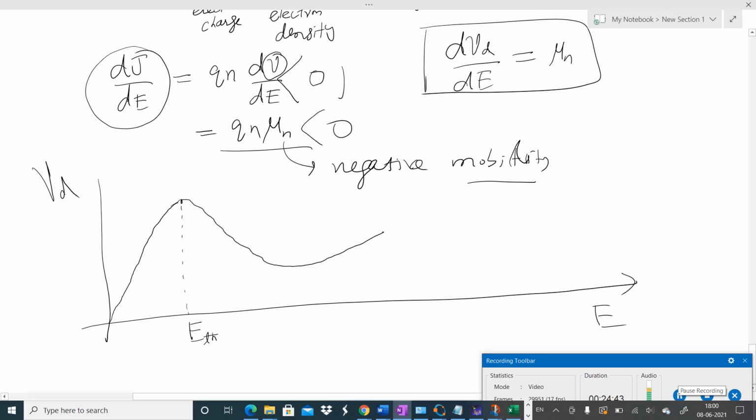And you know that usually, when you have a usual semiconductor, you have this line where mu L is equal to drift velocity by electric field, right? So actually your device should behave like this. Now, because of the satellite valley, because of two valleys in the conduction band, it exhibits this. The moment it starts deviating from the linear behavior, that electric field we call E_L.